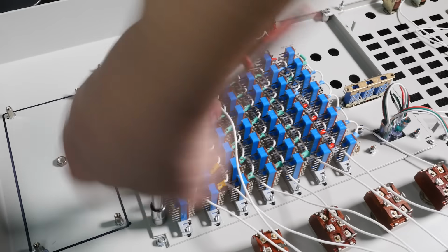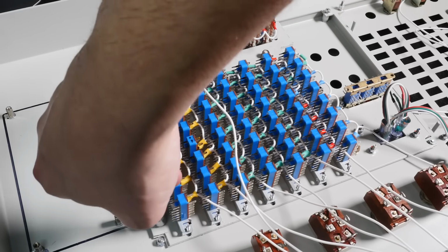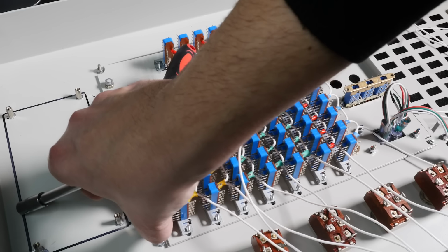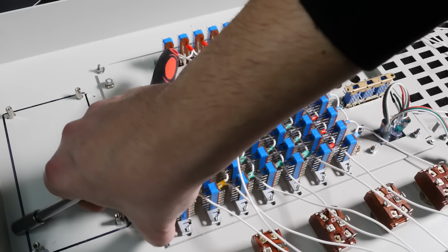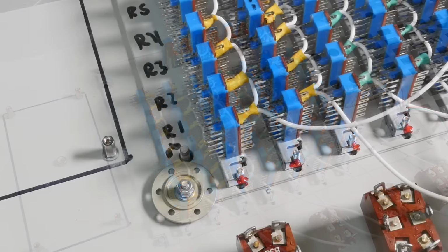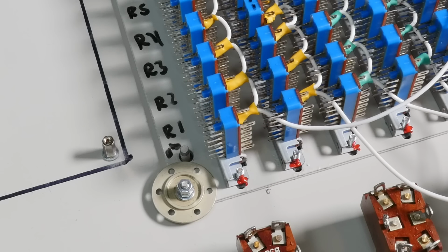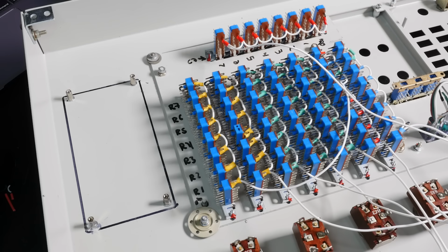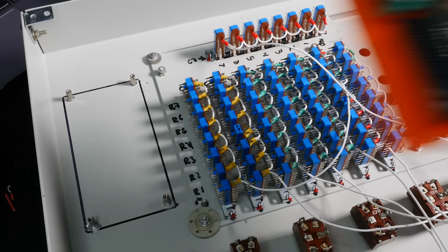Well, very soon I discovered that those studs had apparently been overheated during powder coating. They had become extremely fragile and just cracked. So eventually I had to find another solution and placed those enormous washers. Well, not elegant, but indeed very effective.